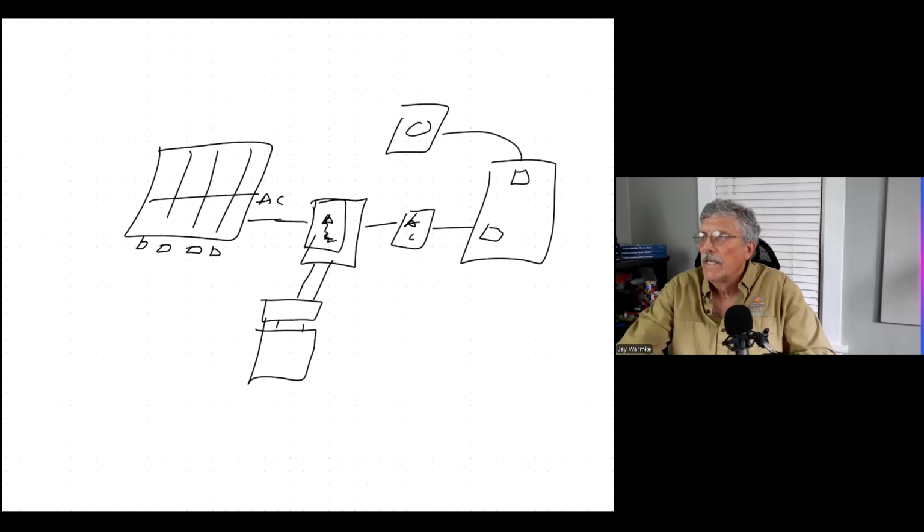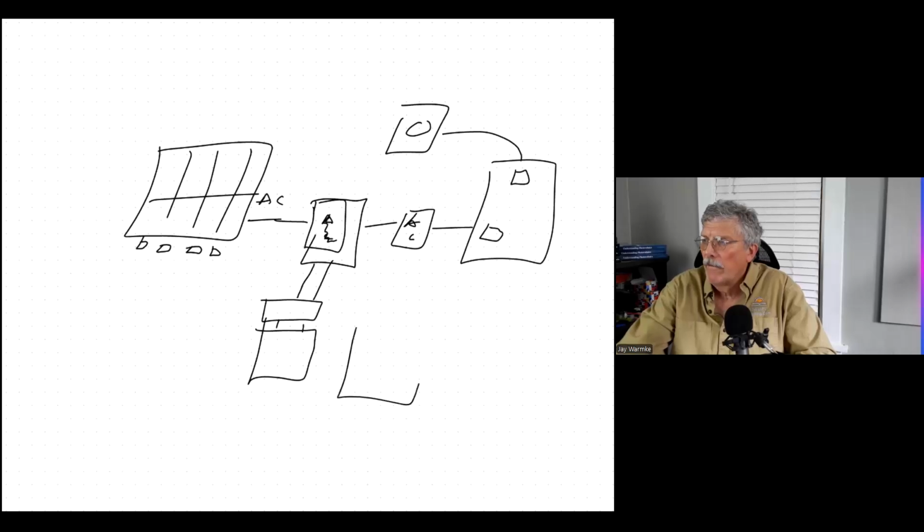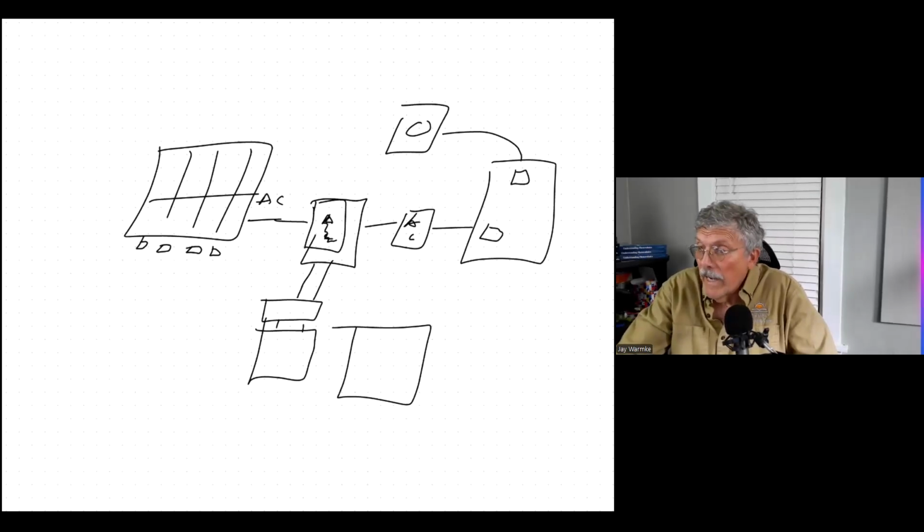It went from DC to AC, then from AC to DC, and then from DC to AC before it ever got to the load. Now, with N-phase, and this is one reason why we have proprietary batteries for these systems, inside that battery pack there is a rectifier, which converts it from AC to DC, and it has microinverters built into it that convert it from DC to AC. And the battery management system and all of that.